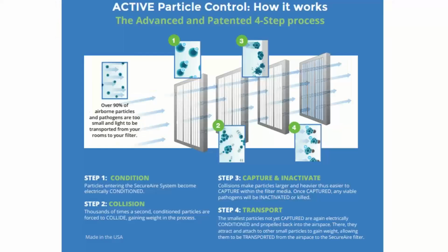So what does this technology from Secure Air do? The thing they have is called active particle control. Write that down. You'll thank me later. Active particle control. What does it specifically do? All right. So first thing is we're going to condition the particles as they're coming through the air. What does condition them mean? Essentially, it means we're going to charge them.